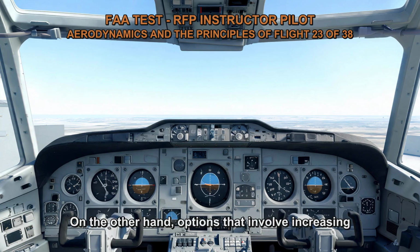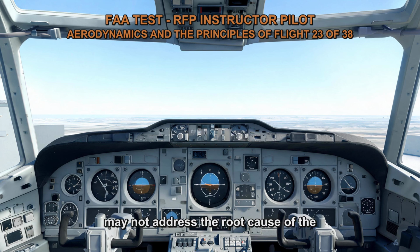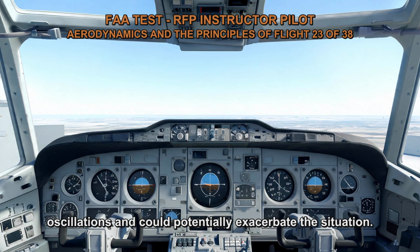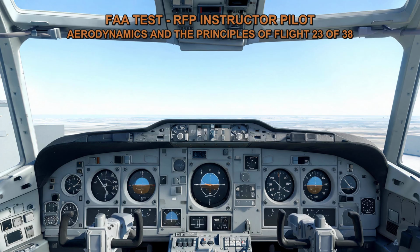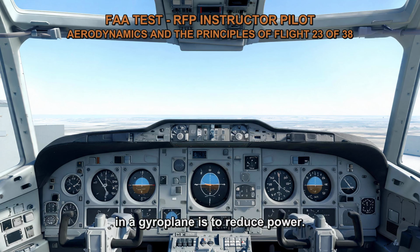On the other hand, options that involve increasing power if nose pitches down or making specific control inputs, such as applying positive forward cyclic, may not address the root cause of the oscillations and could potentially exacerbate the situation. Therefore, the recommended action to reduce pilot-induced oscillation in a gyroplane is to reduce power. This allows the pilot to regain control, stabilize the aircraft, and prevent further oscillations.